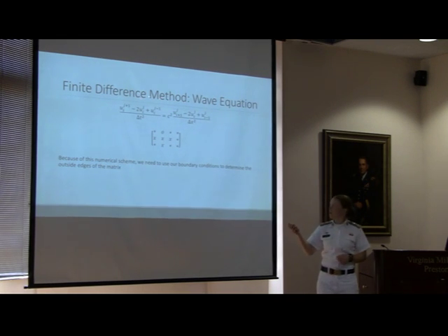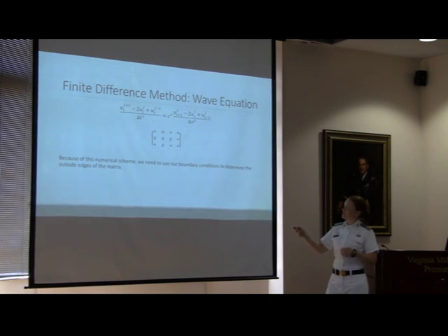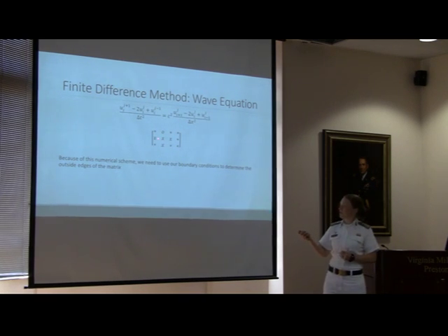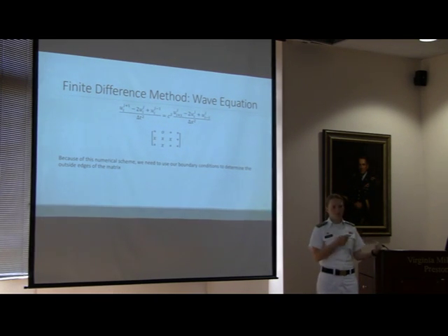So here's for the wave equation. We've got our central difference for second order here, and this is kind of what it looks like. So we're looking at a matrix that represents, we've got time going up in this direction and the length of the beam going this way. So each of these rows is the place of the beam at that time. This here is time 0. This is time -1, which is the reason we need that initial velocity. We can get into using a backwards difference theorem to find the placement back a step in time.